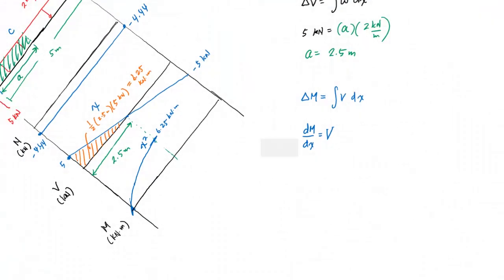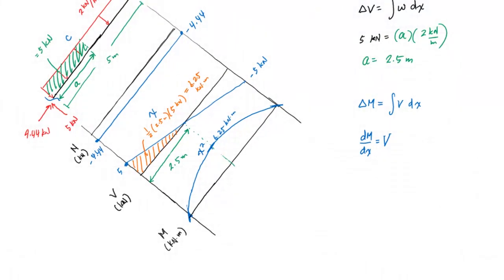And then very similarly, if I look here, it's going to be parabolic again, going from left to right, from the middle to the end of member AB. I have to be horizontal here. I have to have a slope that's -5 here. And so boom, my moment diagram will look like this. All right, so that's member AB's internal normal, shear, and moment diagram.